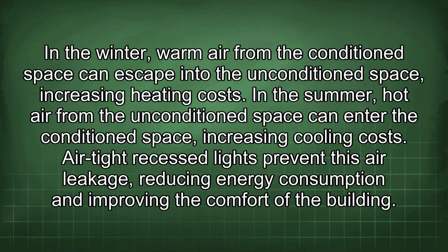In the winter, warm air from the conditioned space can escape into the unconditioned space, increasing heating costs. In the summer, hot air from the unconditioned space can enter the conditioned space, increasing cooling costs. Airtight recessed lights prevent this air leakage, reducing energy consumption and improving the comfort of the building.